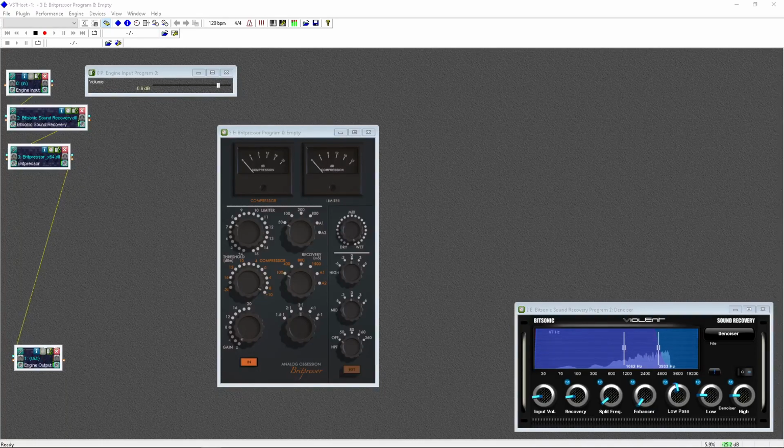Okay, so haven't done much in regards to noise yet. All right, that's coming. So we want just a little bit of limiting. On an S5, or S7, S8, S9 signal, we want to crush it on a 20 over signal, on a 10 over, 20 over. And what that does, so I just changed frequencies. Oh yeah, I'm crushing it now. So that's an S9. So we could probably go back just a hair on that, or we can reduce the gain. So I'm going to leave the gain up a little bit.